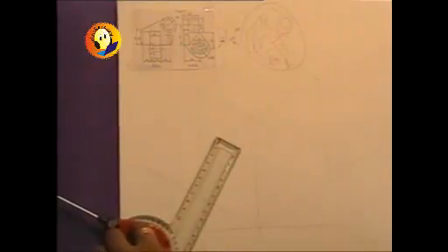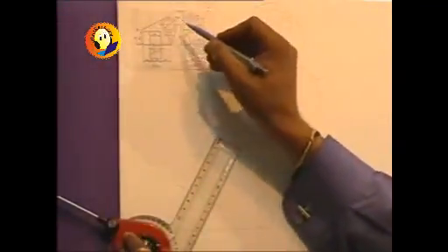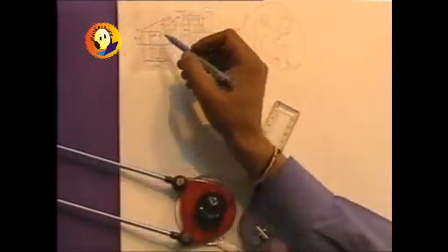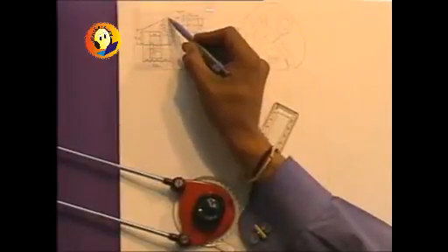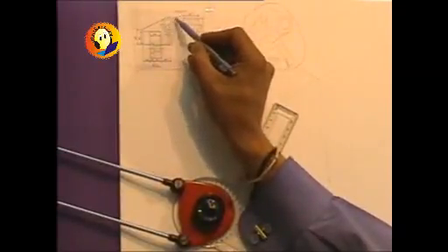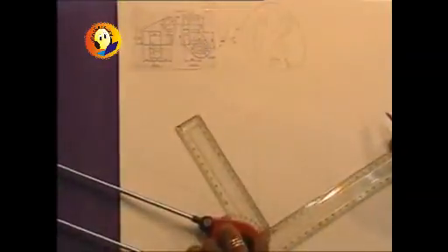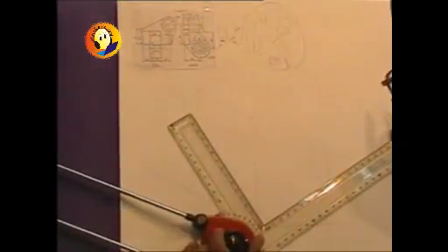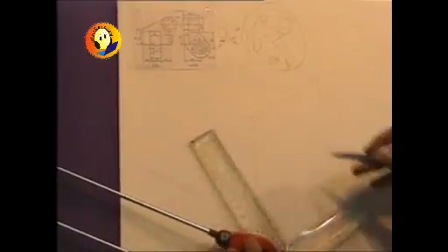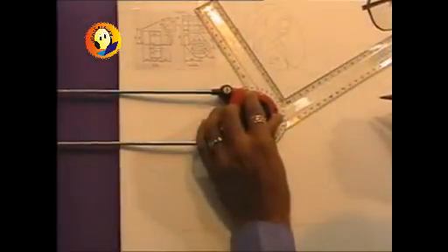Now let us draw boxes for each part, starting with the cylinder, because if you just have a look at the cylindrical part, then I can complete this corner, and then I know that this cylinder is of 50 by 50, so I can locate its box by measuring 50 millimeters, because that is one which can be shown in the front view. So I am marking 50 millimeters,